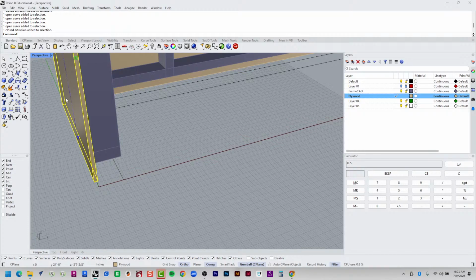When we draw these architectural plans, the structural component of the building takes precedence in the overall dimensioning of the project. Because when we start to make a building, we start literally with the foundation. That foundation would be this 2 foot by 6 foot outline. That would be your concrete slab.